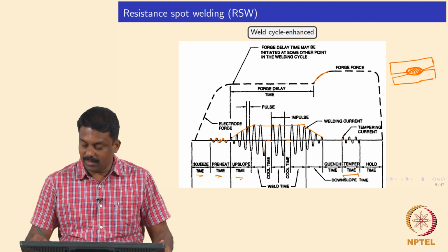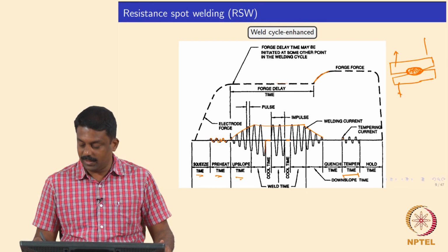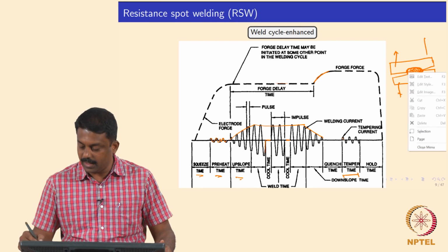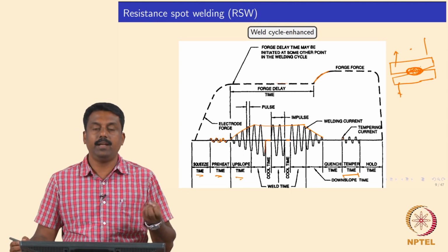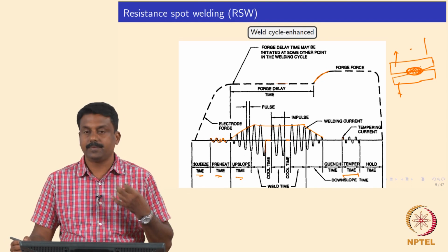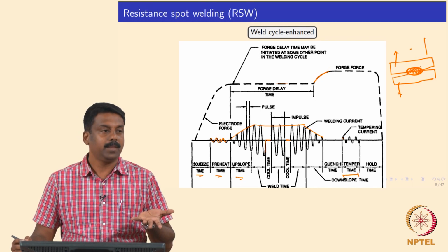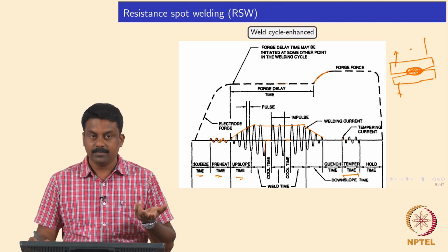So, when you are trying to pull the tensile loading, it is like a notch, and if you have very strong segregation of alloying elements at the weld center, this notch would act as a stress concentration area, and then you will end up forming a crack going towards the weld center line, because the weld center line is the highly segregated area, that is the area where it solidifies at the end. So, you expect the alloying element segregation to make this weld center line very brittle.